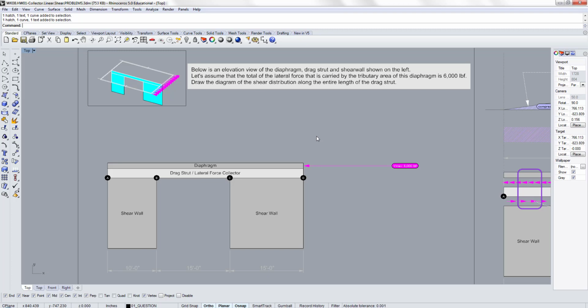And in figuring out how much force this beam needs to resist, we need to figure out how much force is working at each point of this beam, where is the maximum compression and where is the maximum tension, and that way engineers can figure out the worst case to design to, right? So that's basically the idea.